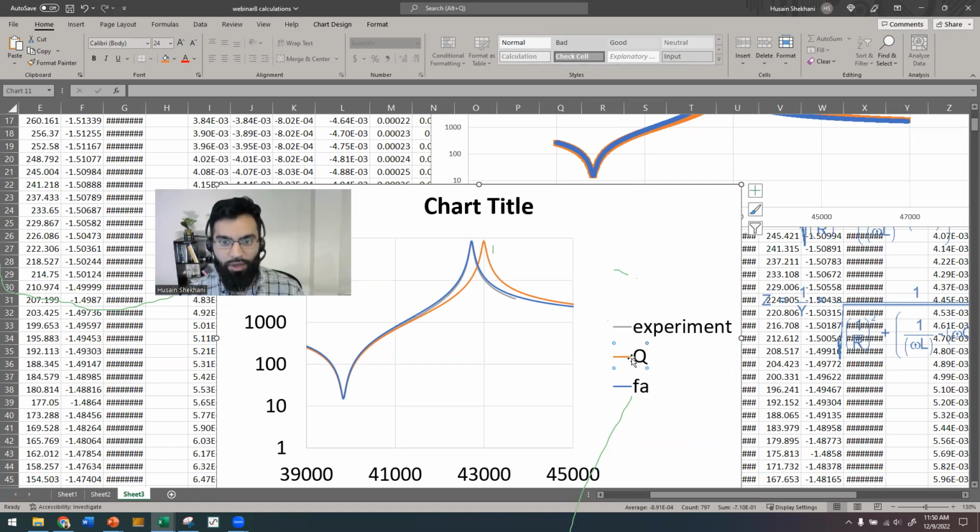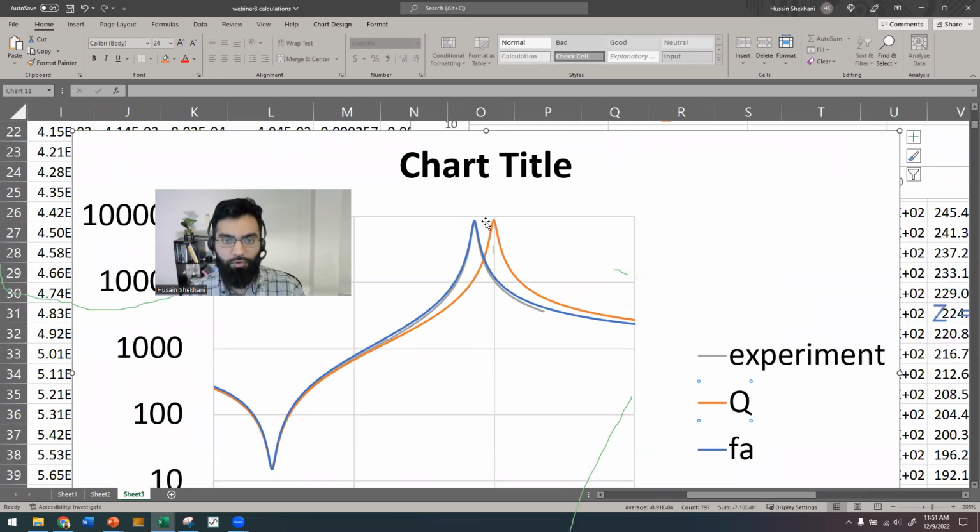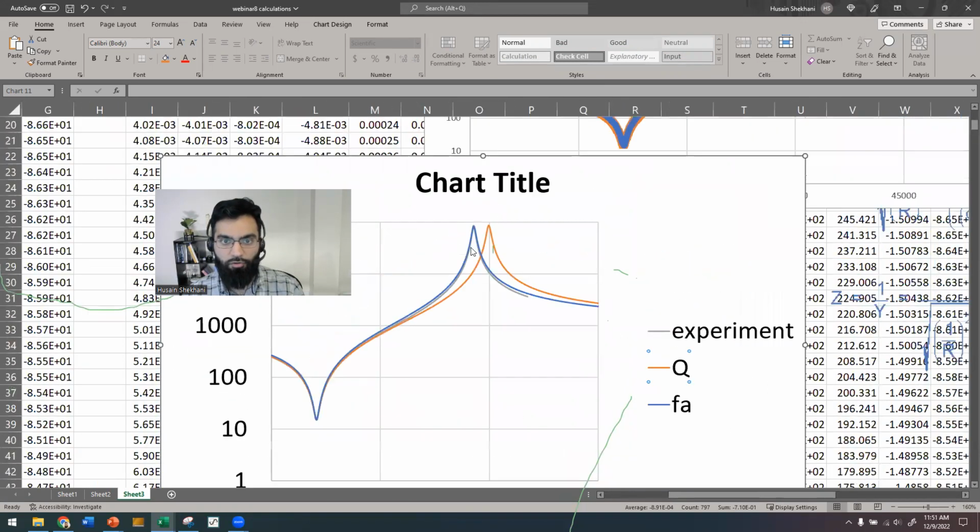Now you may see that the Q method is not accurate. That is probably not true. The Q method is accurate. However, there are probably some nonlinearities occurring at anti-resonance because of the difference in amplitude that causes these differences. So this may highlight the fact that even the small differences between the displacement at resonance and anti-resonance are causing enough nonlinearity to cause an estimated frequency change of however many hertz this is.